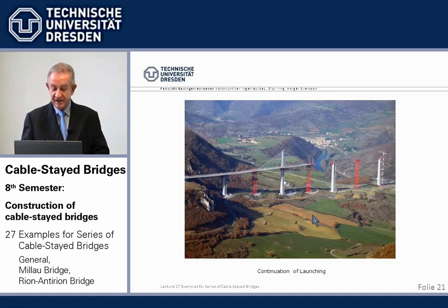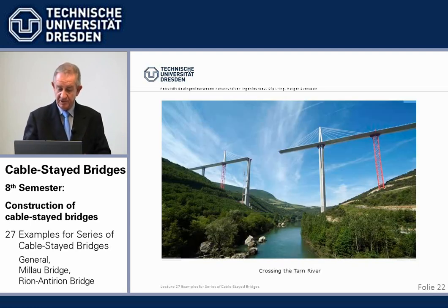And so we see here the launching in full flow. We have here in the main spans auxiliary piers. We have here the launching nose, and we have here this auxiliary tower, which here it so happens stands just on top. That's the way they launched 1,250 meters something from each side to come to about a 2.5 kilometer long bridge.